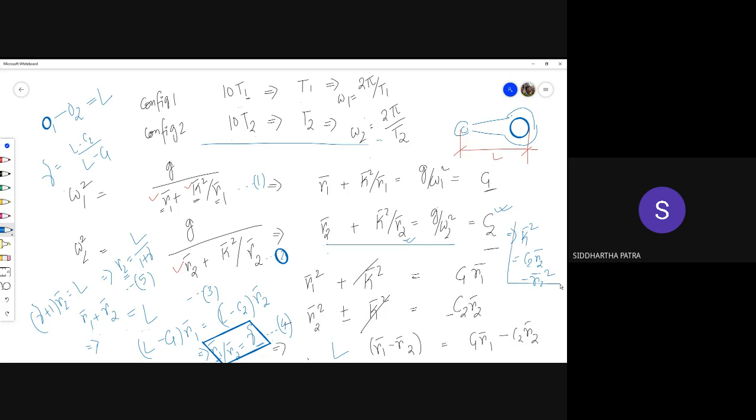So in this way, we can get the radius of gyration of the connecting rod about the center of mass. So it is the radius of gyration about G. How do I get the mass moment of inertia? Simply by multiplying kappa bar squared with m would give us I bar. That's all we need to do in this experiment.